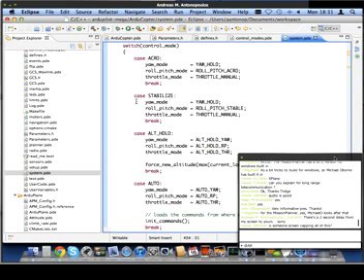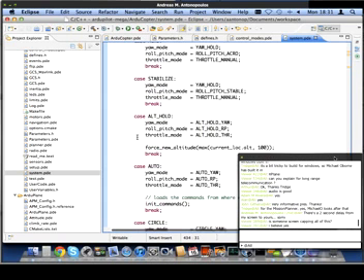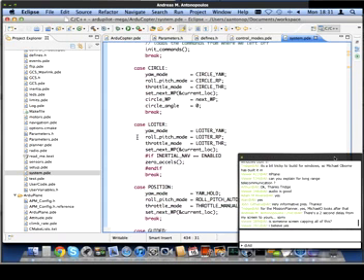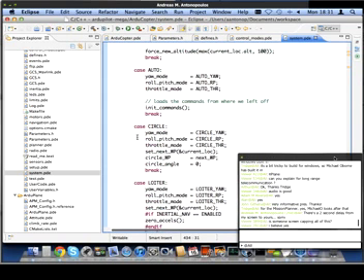This is where it is taking the flight mode, like stabilize or loiter or whatever, and setting 3 other critical variables. A flight mode like stabilize is actually made up of 3 sub-modes: a yaw mode, a roll pitch mode, and a throttle mode. That's a really critical thing to understand.